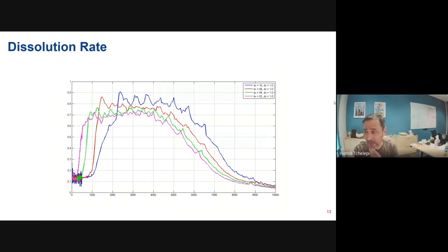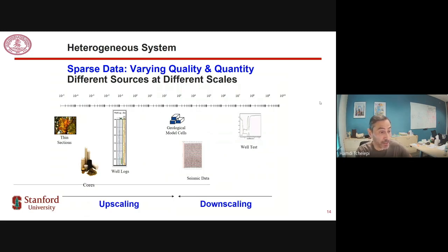And getting the dynamics right also means that the computational resolution of your reservoir simulation needs to be able to resolve the length and time scales associated with the dissolution. There is really significant sensitivity to the resolution before you get grid-converged results of your numerics. Just like with any CFD problem, you have to worry about the convergence rate of your numerical schemes in order to say something definitive about the physics.